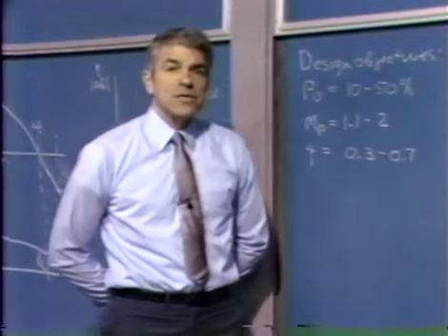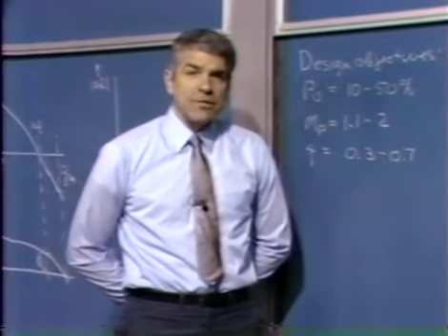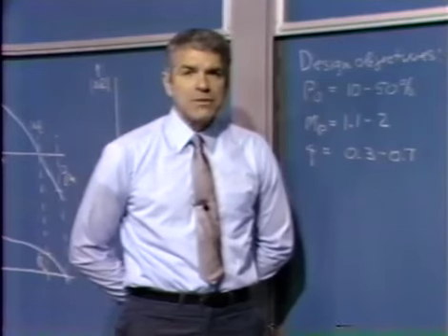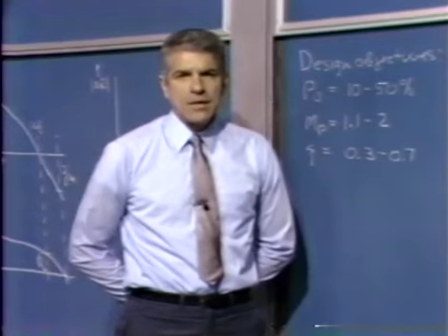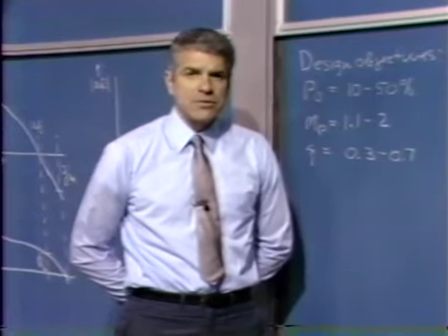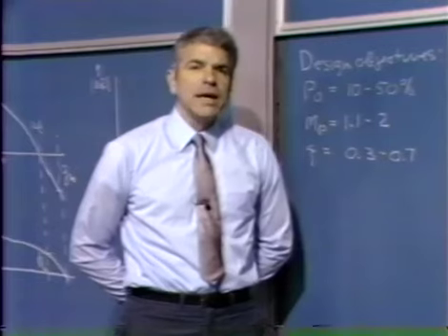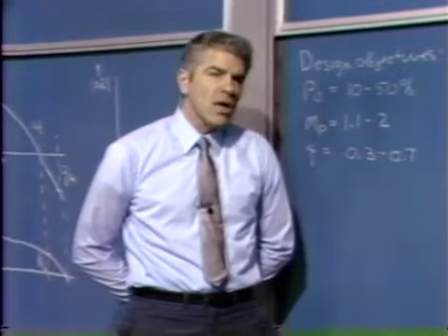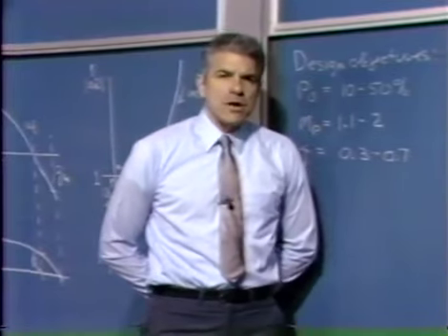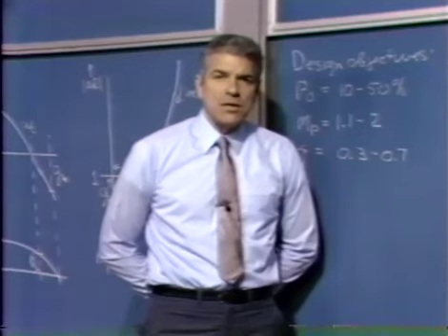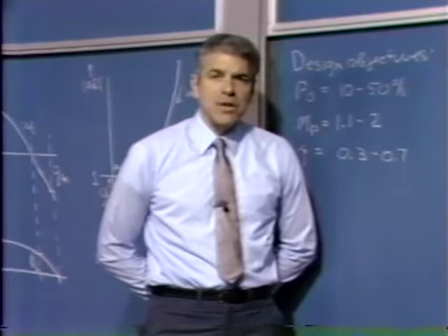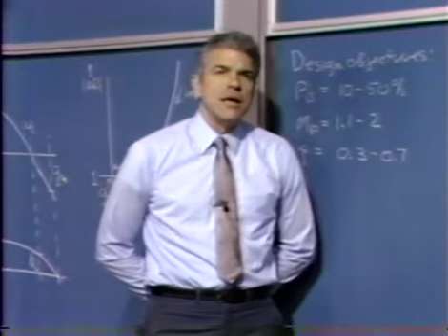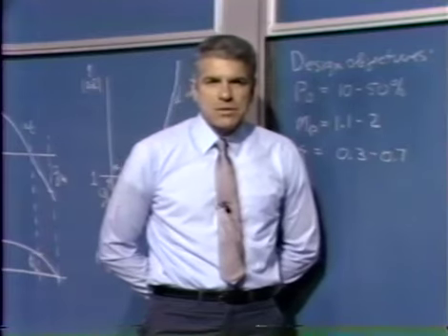But let's consider one possible modification, a very simple one, in particular changing the AF or A0F0 product. We've already looked at that in the earlier example today when we did the Nichols chart construction, and we found out in a very direct way how changes, in that case in A0, affected Mp for the system. What we assumed in doing that construction was that we were able to change A0, change the magnitude of the loop transmission, without making any change in the angle associated with the AF product. And that is realistic in some cases, but not always.